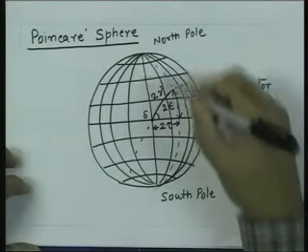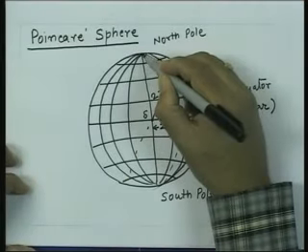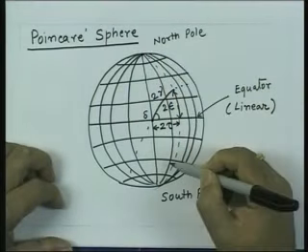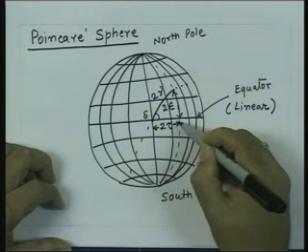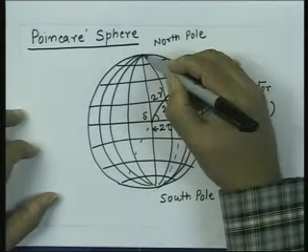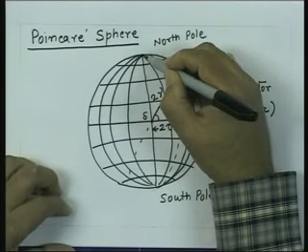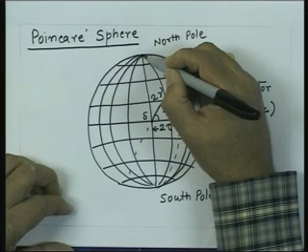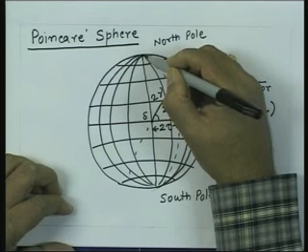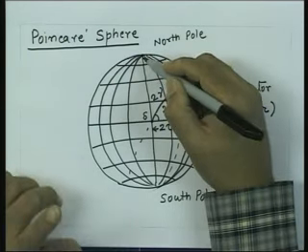Let us take some other special points. Let us say I take the point which is the North Pole. Now, for North Pole, the 2 epsilon has become 90 degrees. So, the epsilon has become plus 45 degrees. If epsilon is plus 45 degrees, the axial ratio for this is equal to 1, and if axial ratio is 1, that represents a circle.